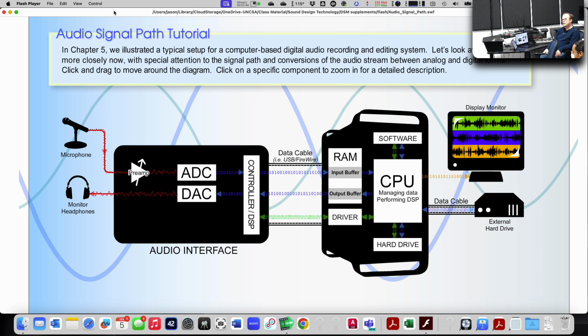And it does that by taking what are called samples of that electrical signal at some predetermined interval. And that interval is called the sampling rate, and it needs to be at least twice as fast as the highest frequency of audio that you're wanting to represent. So generally speaking, the lowest frequency that we tend to work with from a sampling rate point of view is 44,100 hertz, or 44.1 kilohertz. We usually don't sample at a lower rate than that, except in some very, very rare exceptions.